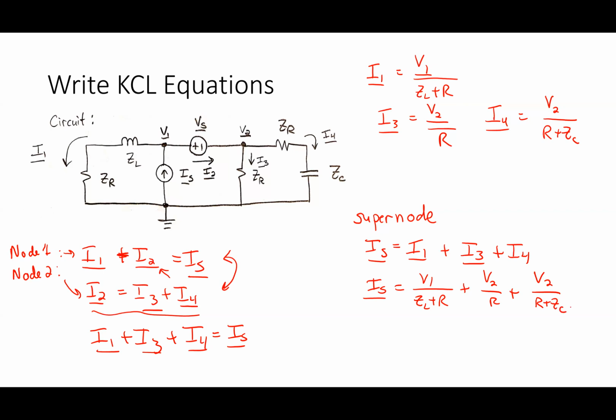So step back. If I want to make this work, how many equations do I need here? Two, because I've got two unknown nodes. This is one, and it's got two unknowns. What's the other equation? It's the one that comes from KVL, so it better be just in terms of voltages. What's the KVL relationship that I get in this case?